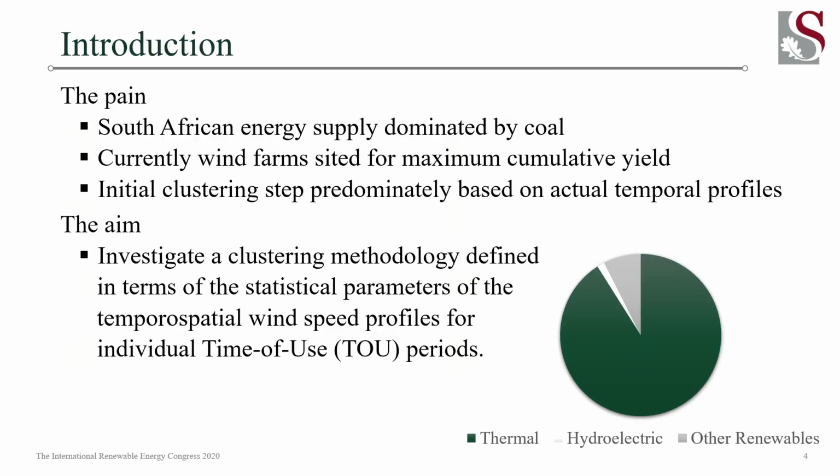In this paper, we focus on the South African region, where South Africa has an energy supply which is dominated by coal. However, the concept in this paper can be applied worldwide since there is a growing penetration of renewable energy, especially wind energy. This increases the operational challenges induced by the variable nature of these sources. These challenges include increased use of peaking generation and ancillary services, as well as increased ramping of conventional power plants. Now, the variability and uncertainty of the renewable resource furthermore complicates the short-term forecasting of the associated generation profiles.